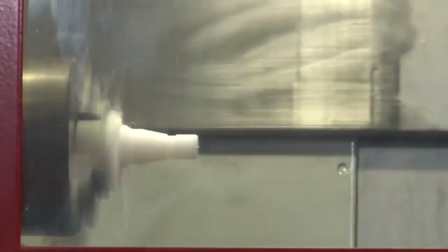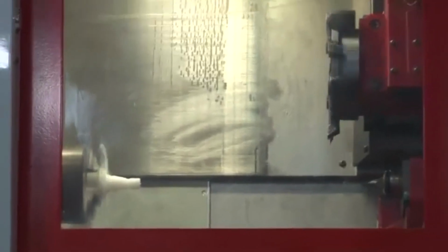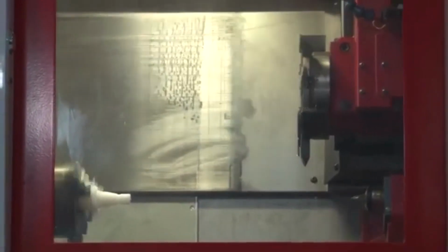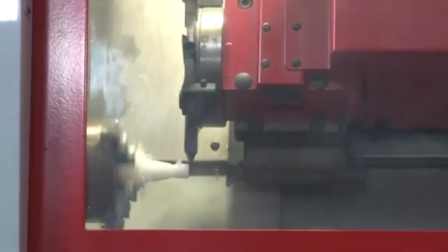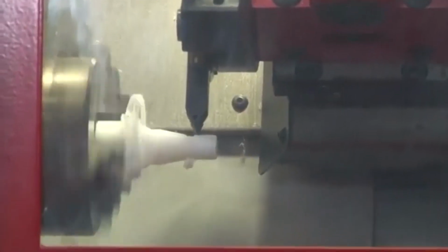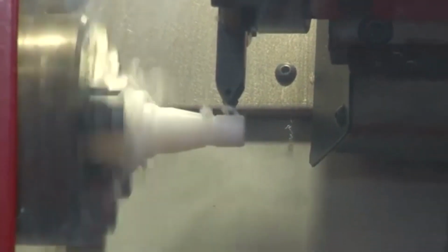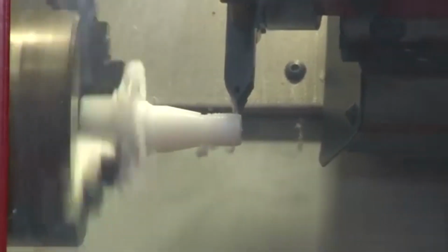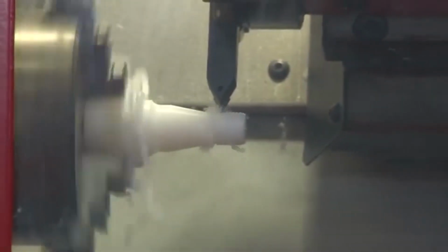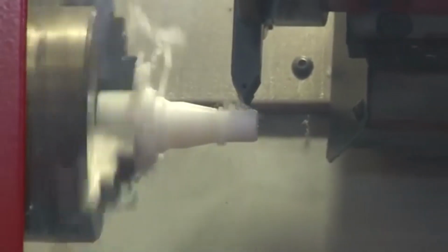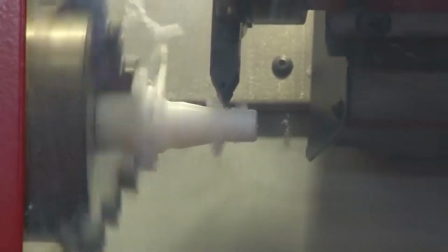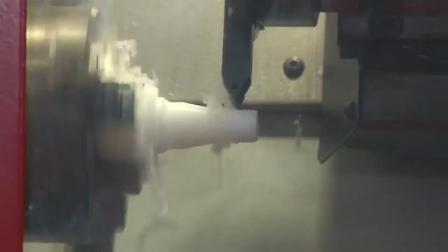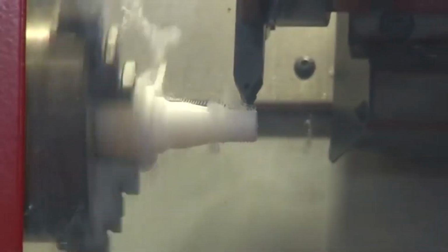And it is done in various passes. Then it will again go back to the initial position, and then another tool is selected, and that tool is the threading tool. So, you can see the threading now is done, and see the speed is decreased in case of the threading operation, and in several passes with incremental depth, the thread depth has been achieved. This is how the threading is done with the threading tool.